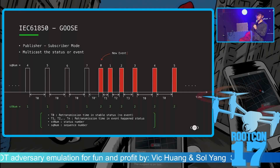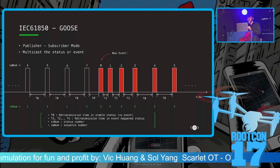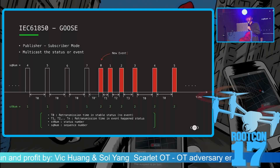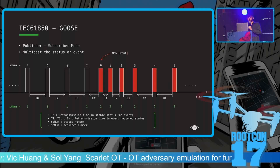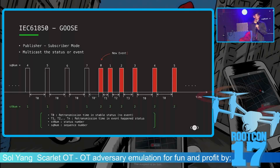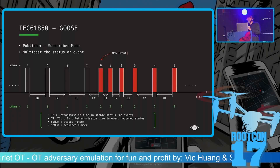It is a protocol for broadcasting events. When no new event comes out, the old event is broadcast all the time, and the value of sqNum increases. When a new event happens, sqNum resets to 0 and stNum increases. What we want to do here is to sniff and fake these two values.